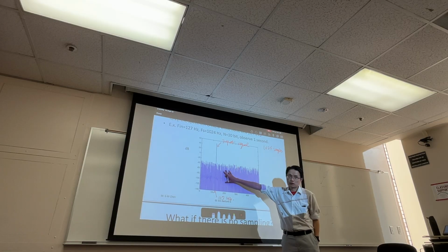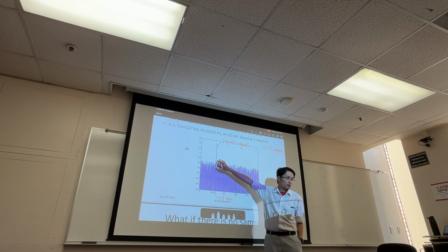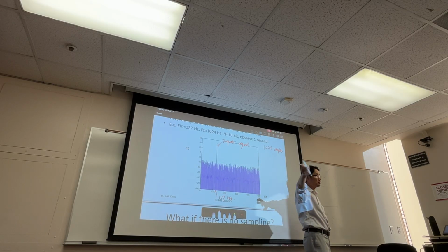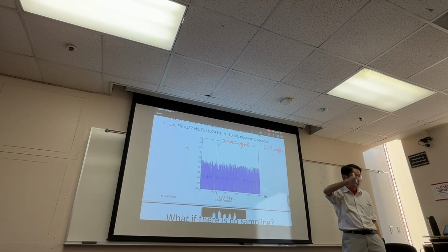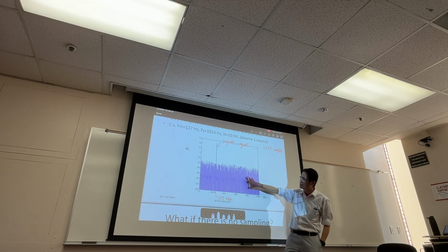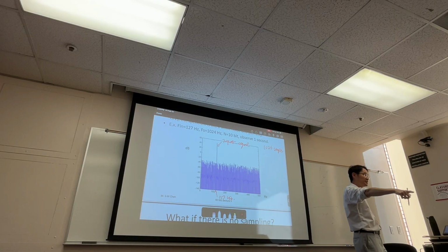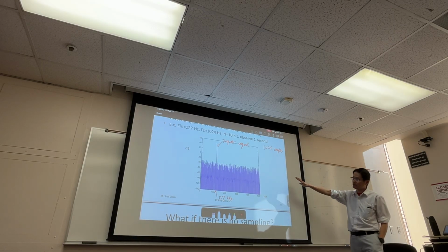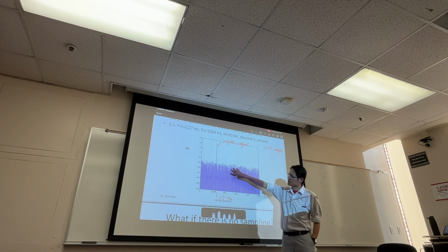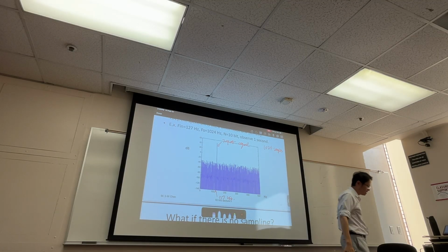What are these? So I do see this guy, this is my input, which is a sine wave. That's a beautiful sine wave, no problem. What are these? Quantization noise, right? That's the error that we just analyzed. What kind of noise does this look like to you? White. What is a white noise?